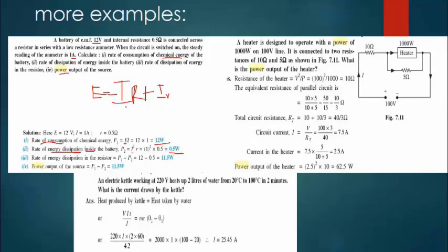Therefore, to get the power that passes only to the external resistor, it is equal to the power generated by the whole battery minus the one that the battery itself consumes. It means all that is remaining is passing to the outside resistors. Similarly, when he speaks of the rate of dissipation of energy in the resistor, the total power that the battery can offer is equal to the power that goes to the resistors externally plus the power that is lost as heat in the internal resistance.